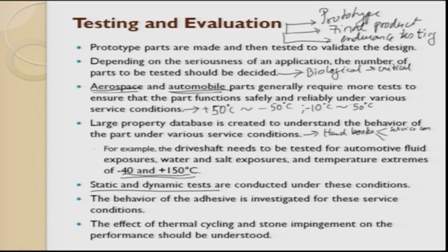Static cases, okay, we do a tensile test only for one component, but what happens as and when the component is dynamically loaded and unloaded? What is the response, the deterioration of this product or this property? This is very important. Today we have started looking into dynamic testing also. That means we apply a fatigue cycle or some cycle, compressive cycle, tensile cycle, compressive tensile loads, so that we get the output. So static and dynamic tests are conducted, and then we try to take the conditions out.